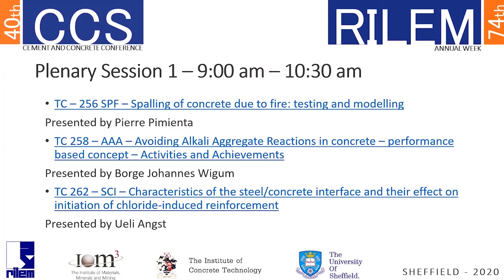Okay, there is also a question with regard to the chloride diffusion test, NT Build 492. Is there a weakness of the standardized tests if you want to use this to study the behavior of the chloride ions, according to your opinion? So this test primarily is a test to characterize the transport of chloride through the concrete.